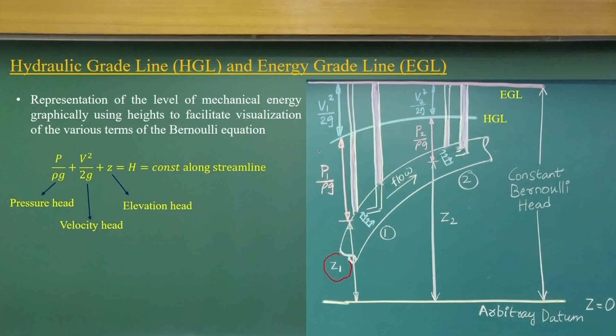That means, as an equivalent, if I have a liquid, how much it will lift because of the pressure, the flow energy, the kinetic energy, and the potential head. That is the reason we define it as head: the pressure head, velocity head and the elevation head. There is nothing else; they are all three energies, the flow energy, kinetic energy and potential energy, constant along a streamline.